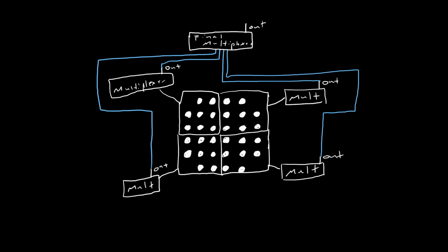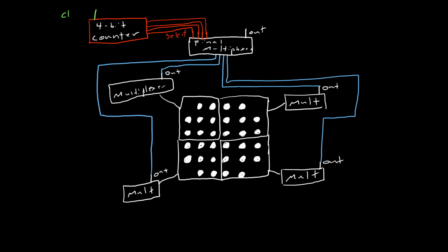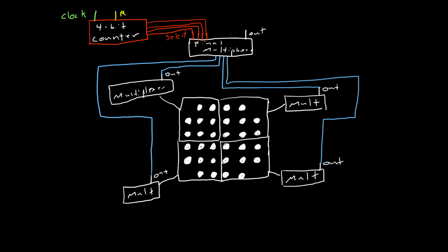At this point it would require 7 pins to address the individual pins in the matrix, and 1 pin for the output. Even this is too much for the microcontroller, although there does exist an easier method. Instead of addressing from the microcontroller, we will offload that duty to a counter IC. Each time we wish to see the output of a neural electrode, we send a pulse to increment the counter by 1, selecting the next pin with the multiplexers.